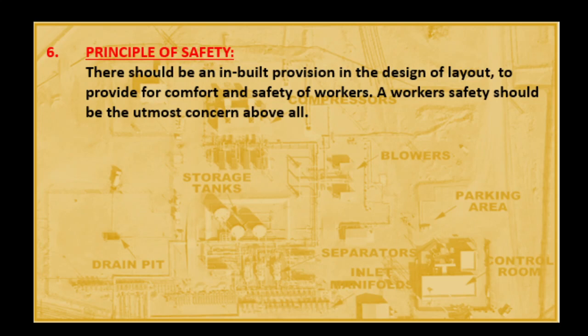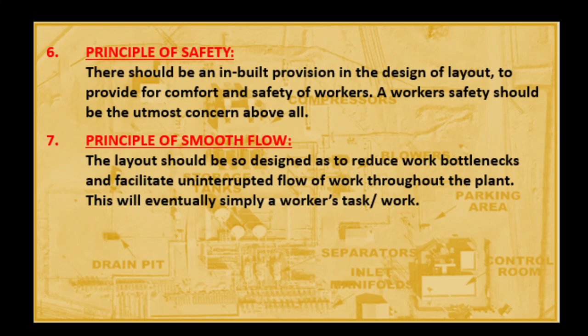So seventh principle na consider natin dito, tinutukoy natin principle of smooth flow. The layout should be designed so as to reduce work bottlenecks and facilitate uninterrupted flow of work throughout the plant. So in the end, this would eventually lead to simplification of the worker's task or work in hand. So in this case, the smooth flow of work due to proper layout reduces the possibility of work accumulations or bottlenecks, which is considered to be the advantage of the worker.